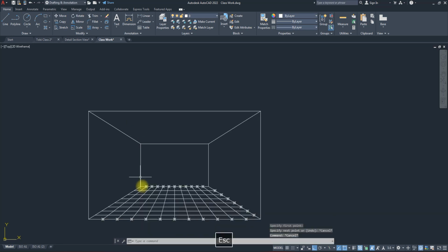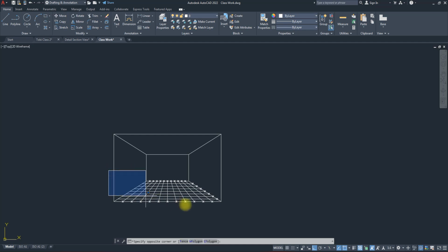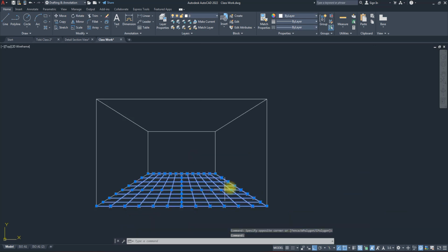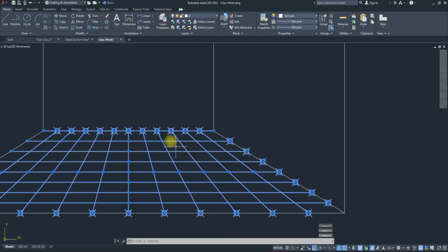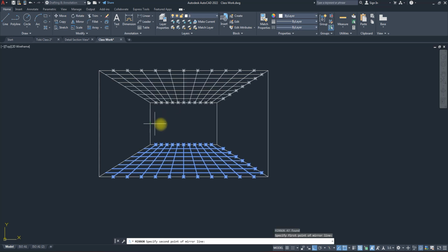Actually, I am still going to subdivide this top to simulate that, because it will not be on this line. It has to come out a little bit. So to make everything easy for myself, I can select all these lines except this one. If I hold down shift, get rid of this, get rid of this, and then that, all the surrounding lines, I can mirror. Let's see. If I say MI for mirror, I can pick this as my mid line. Then that would have done that top part.